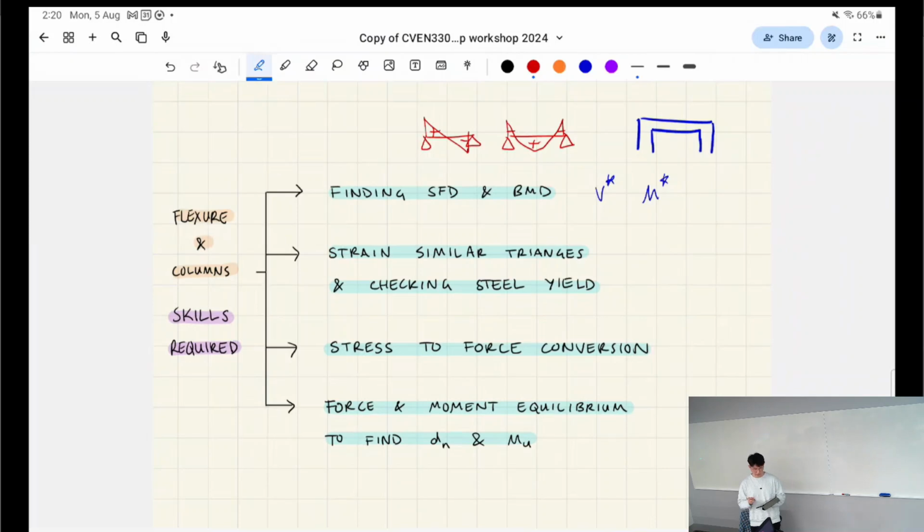Another thing to note is, you might also see continuous beams, right? And we don't necessarily learn how to solve continuous beams in 1300 because they're statically indeterminate. There are too many unknowns, so you can't solve it using the normal methods that we learn. But instead of using the methods that you learn in structural analysis, 2303, the concrete standards have a simplification method that's listed, and it's a lot faster to follow those formulas than trying to use the methods you find in 2303.